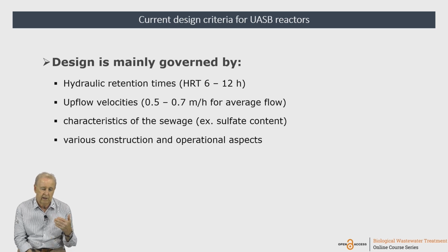In other words, the hydraulic retention time is the main design parameter for sizing the reactor, for determining the volume of the reactor. Also, the outflow velocities, I'm going to talk more about this in the next slides, but also by the characteristics of the sewage.